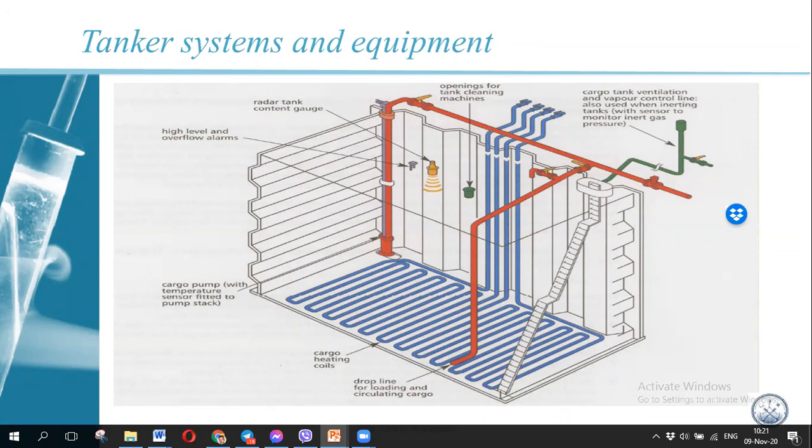In case you are planning to do circulation of the cargo, that is also part of this. You start the pump here, open this valve, build up pressure, open the valve, keep the manifold closed, but open this line, and the cargo will go here. So you are taking the cargo and dropping it in here. Why do you need to do this?